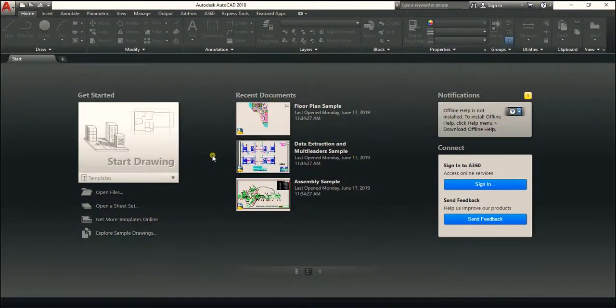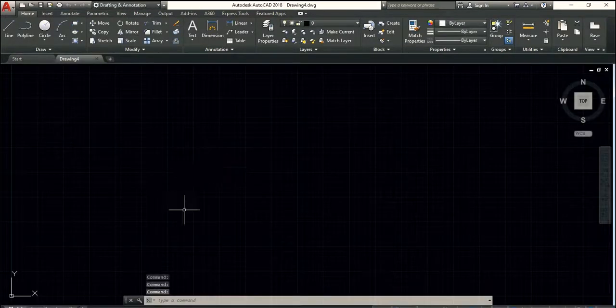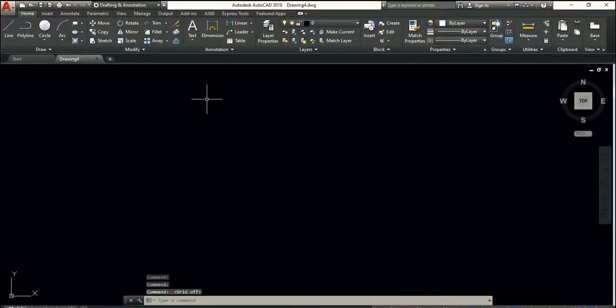Alright, so I'm assuming you have a knowledge of AutoCAD 2D now. So for you to start up your project, you would have to start your normal drawing, just like you would in AutoCAD 2D. So if you click this to start, you have a new drawing. Then you know that for you to get rid of this grid, you click on this or F7, then the grid goes. So now by default you are in the drafting and annotation workspace, and this workspace is meant for 2D drafts, which I suppose you know.